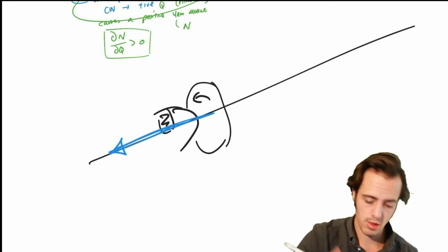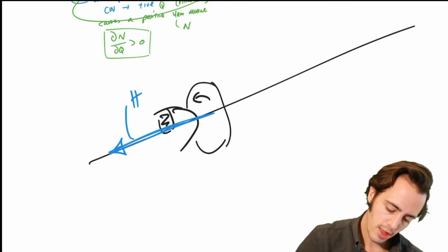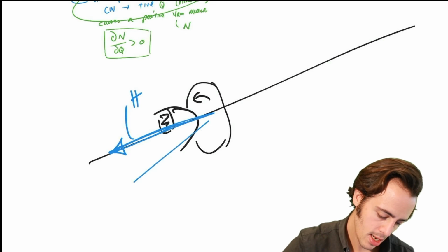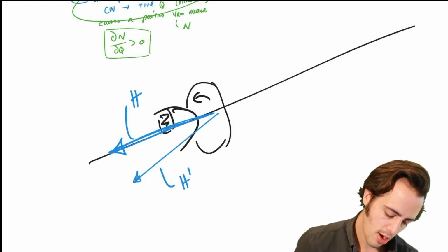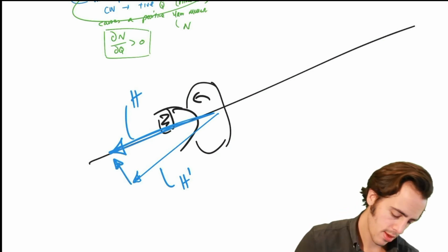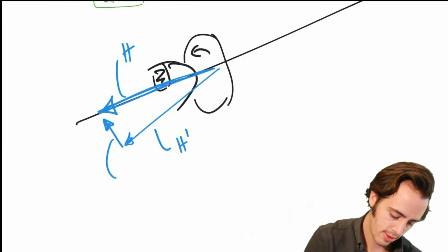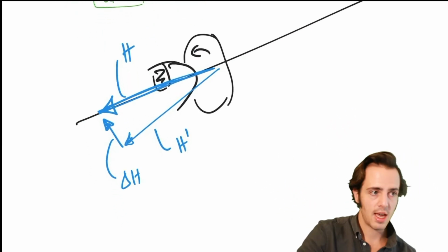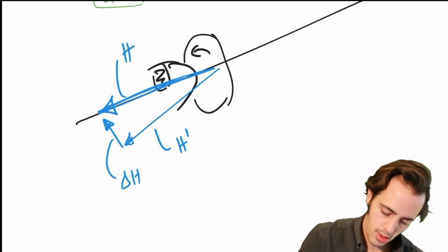That's the convention for angular momentum. So again, a positive pitch rate would cause the angular momentum to shift to this position, to H prime, and in order for the total angular momentum to be constant, we'd have to have this vector produced, which is this delta H, and this then, thumb upwards, gives us a nose port.